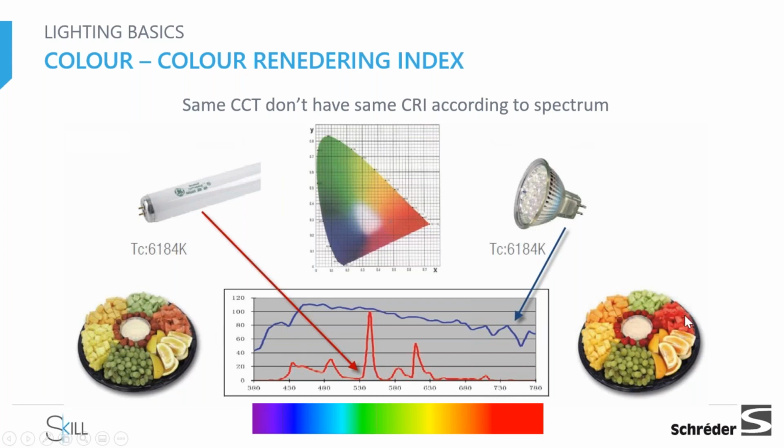You look at this and you compare this. Because this fluorescent light source does not have the red color, you will not be able to see the red color of the melon here. Orange, it will not have orange, look at the orange here and then compare it with here. Here they have yellow, so the color of the orange will shift to yellow, and I'm not able to distinguish if this is orange or yellow or lemon. Green for the grapes and the kiwi, they are almost the same if you notice. Why? Because we have a high green component in the light source spectrum.